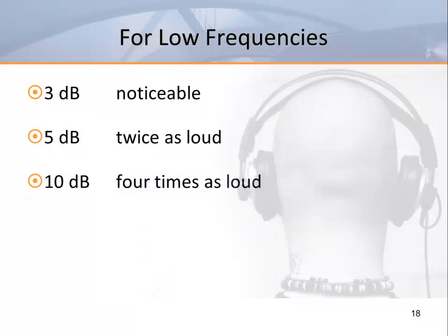It's safe to say that we are twice as sensitive to low-frequency sound than we are to high-frequency. That's why low-frequency sounds generated by motors and blowers are the most frequent cause of noise complaints. It only takes 3 dB of low frequency to be noticeable, 5 dB sounds twice as loud, and 10 dB sounds 4 times as loud. In terms of NC, we can say that for a fan-powered product, an NC35 unit sounds twice as loud as an NC30 unit.